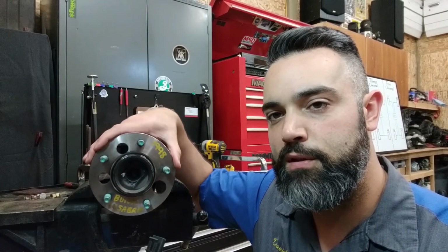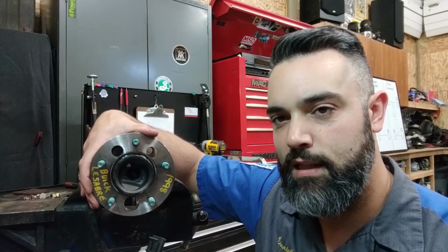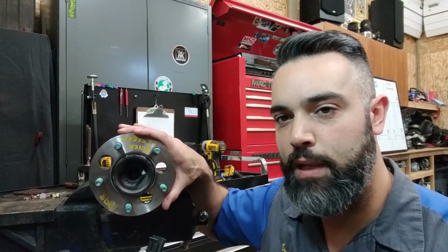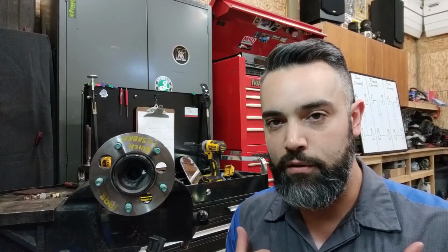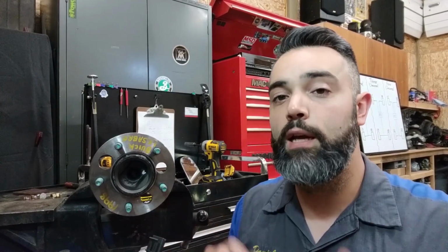Isolate, reduce, reapply. Isolate, reduce, reapply. And that's the basic concept of how ABS works. Now it's doing this many times a second, and it could be monitoring the rear axle, each individual front wheel, or all four wheels individually. Depending on the type of system, how many channels it's configured with is going to determine what the overall outcome is going to be with the system in operation.